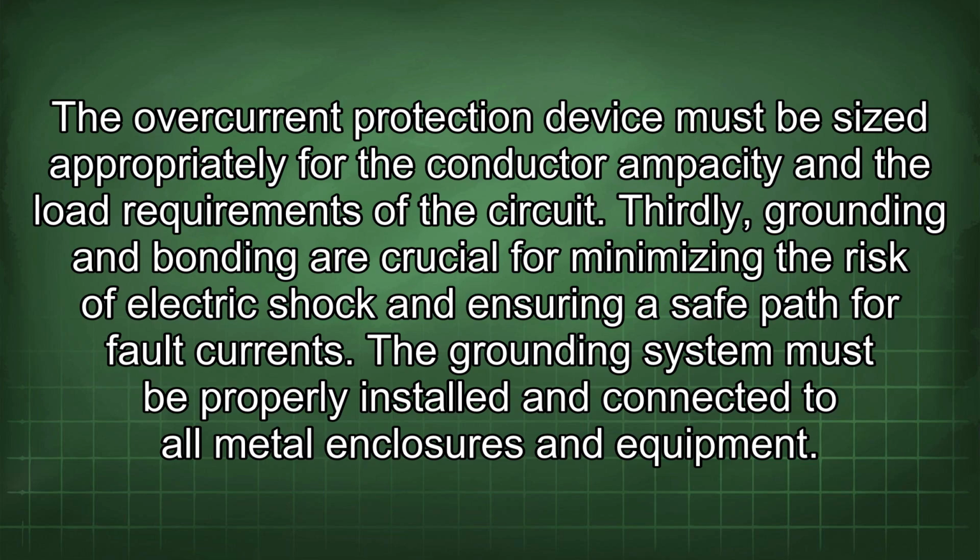Thirdly, grounding and bonding are crucial for minimizing the risk of electric shock and ensuring a safe path for fault currents. The grounding system must be properly installed and connected to all metal enclosures and equipment.